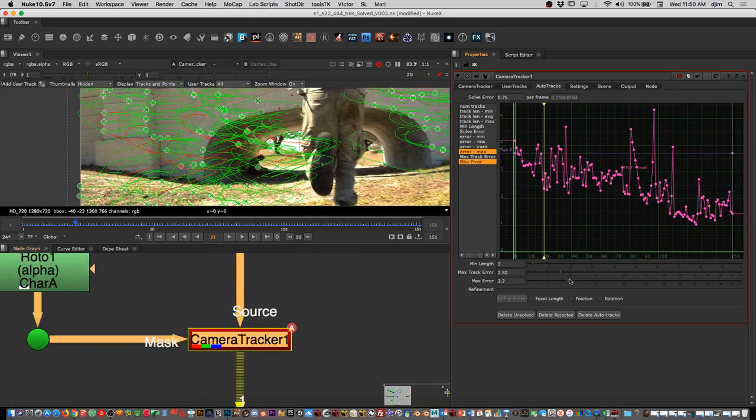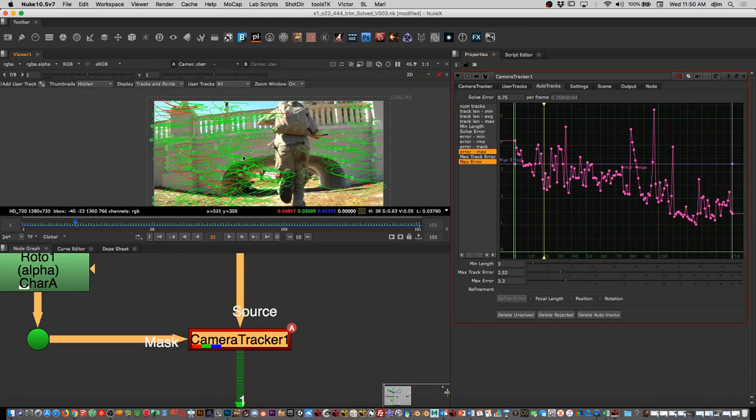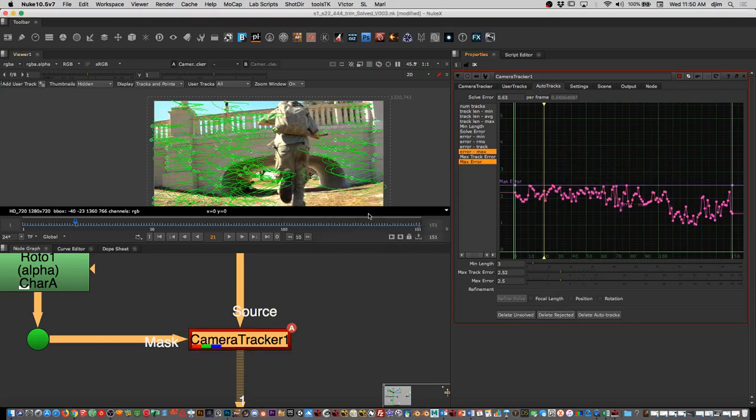So let's go down here, and you can see the knife. As the knife keeps going down, you notice that something happens on your screen. A lot of those trackers start showing in red. And what that is telling you is that all those trackers are above the threshold line. So I want to delete, reject it. I'm going to hit yes, and all those trackers just got cut by that threshold.